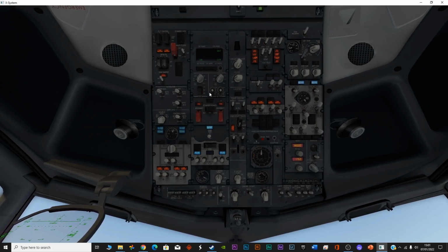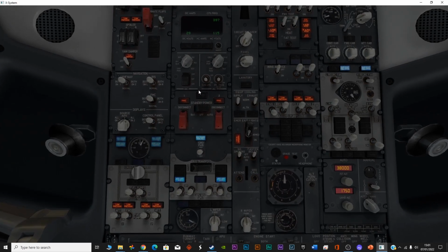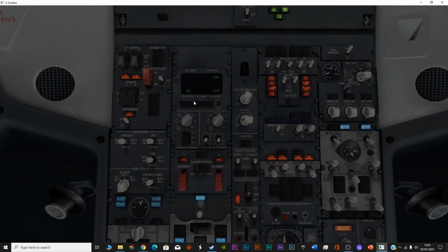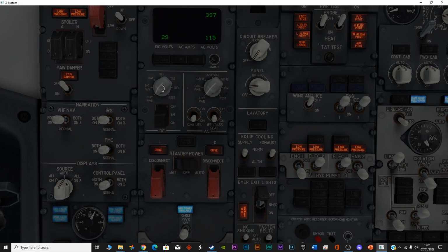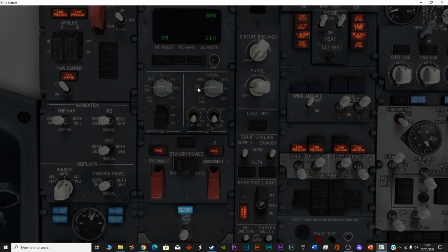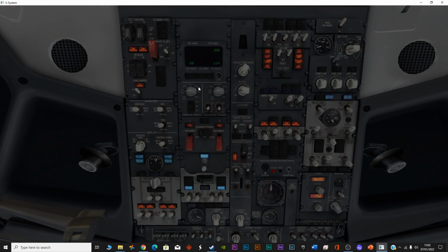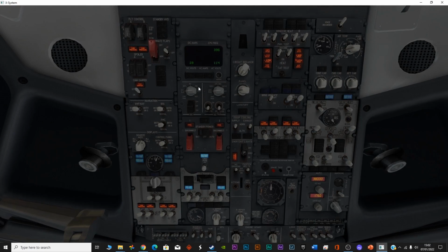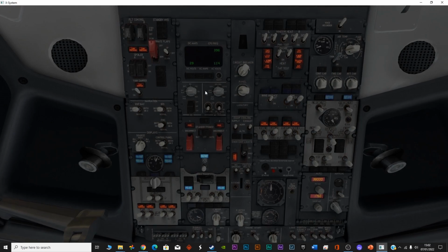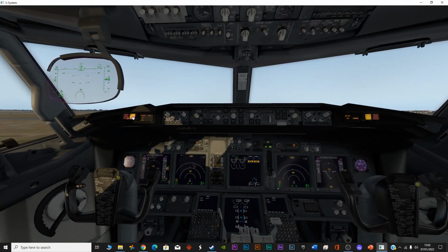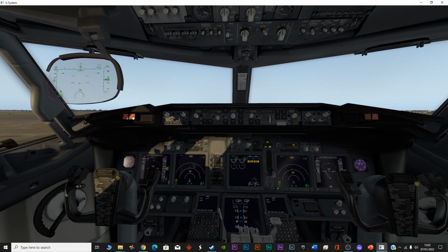and if you want to see the voltage of the ground power and the DC plus the AC power, you can switch the DC to battery, and you will see the voltage. It was already coming, and you can turn it to ground power. You can see how many volts are there. So you can also use the DC and AC voltmeter selectors to see if the proper power is coming or not. At this stage, disengage the master caution.